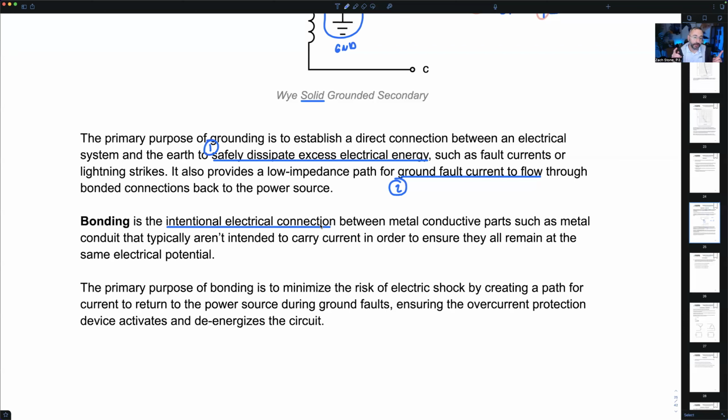And then we combine bonding with grounding. So for example, if I bond my washing machine or my clothes dryer, which it is, right? If that connection occurs, a lot of vibration occurs, the wire gets rubbed raw, and now the metal conductor of the wire is directly touching the metal case. Well, if it's bonded, it's no big deal, because that metal case is already directly connected through the equipment ground conductor all the way back to my panel in my garage where my breakers are.